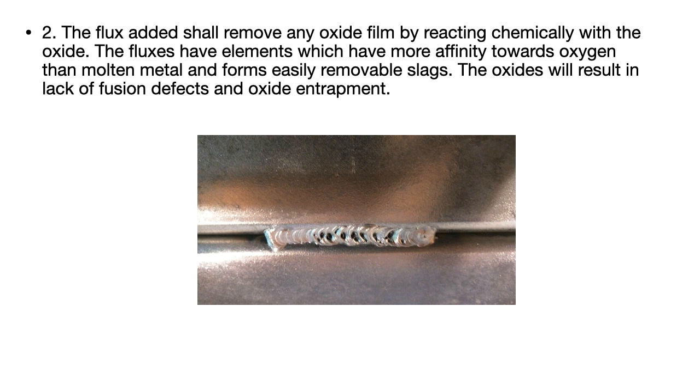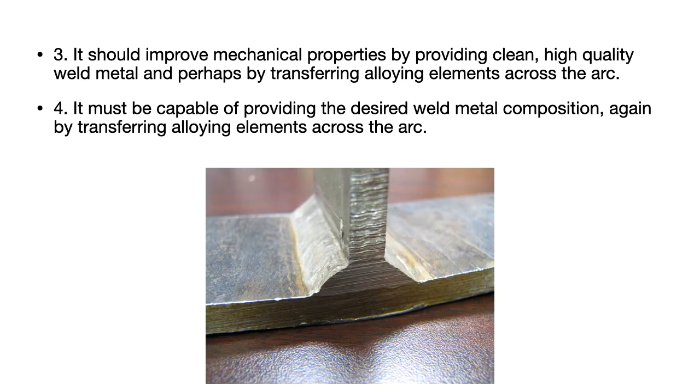The defects which can be produced due to the presence of oxides are like lack of fusion. The fusion may not be proper, or the oxides can get entrapped. The other is that it can cause porosities. One of the defects, porosities, I have shown in this slide.